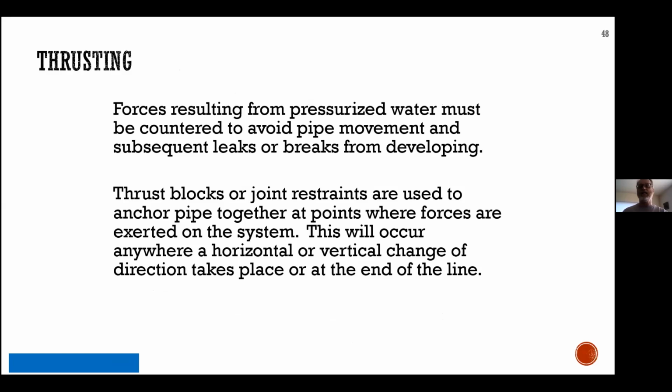So how we do that in the system, because if we've got to turn the water pipeline 45 or 90 degrees to go down the next block, we have to protect the water main. I'll bring up some videos when we're doing the pipeline and pipe materials, because there are a lot of different types of joints in pipelines that are either push-on, bell and spigot, or bolt together, flanged, or something in between like a mechanical fitting. They are designed for different applications.